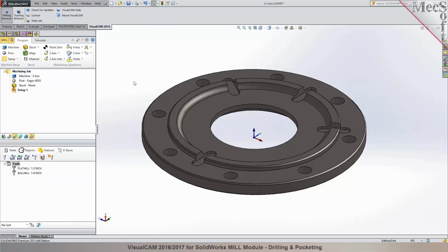Okay. All right. So the next step is, since we changed the orientation, the setup is flagged dirty, so we just right-click and regenerate. That'll update the setup to ensure that the orientation for machining is defined, so it's normal to the space right there. We are now ready to create the stock geometry in here.